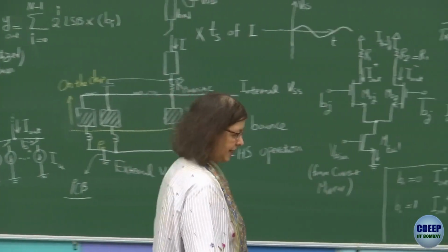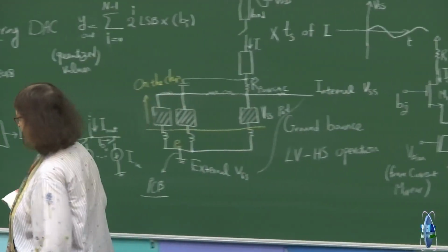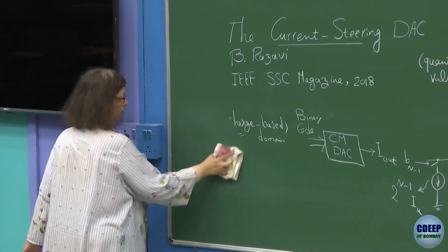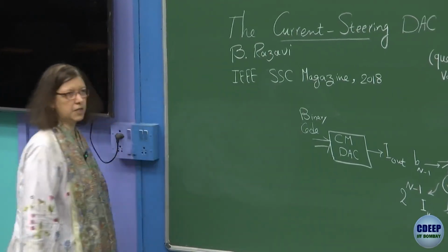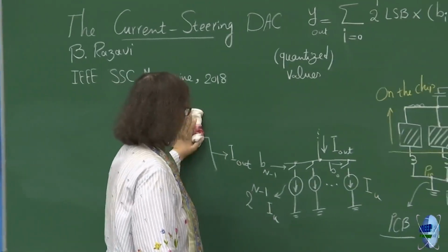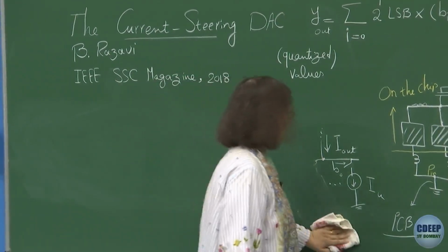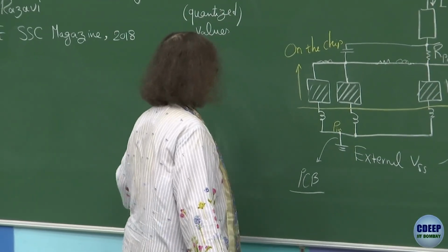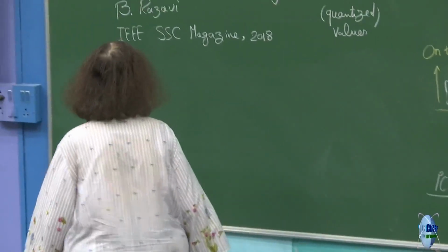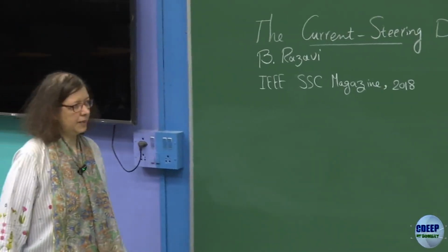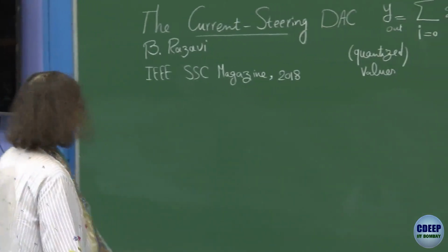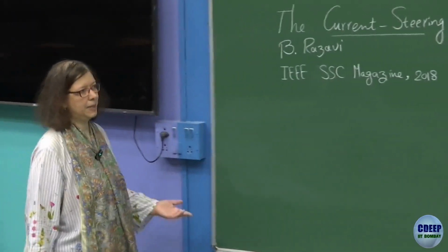Now, we didn't have an opportunity in the SAR ADC to get rid of this problem of matching. Of course, there are calibration techniques which actually adjust the values in the software and sometimes even on the chip, this mismatch issues. Layout also, of course, is very important. We had some discussion about layout of capacitors, and in reference paper from Leo also you have seen the arrangement of capacitors on the layout. But here there is an opportunity which didn't exist over there, and that comes because these are all current sources which eventually can be made parallel.